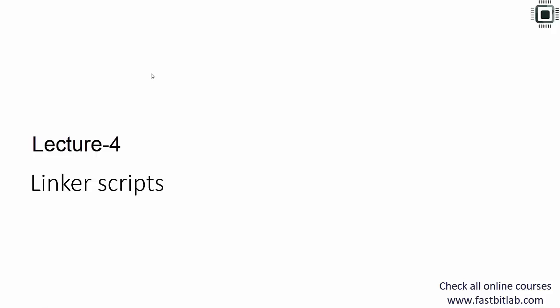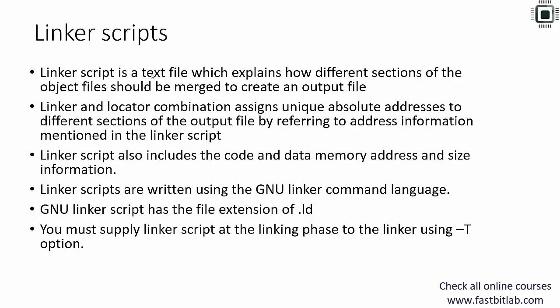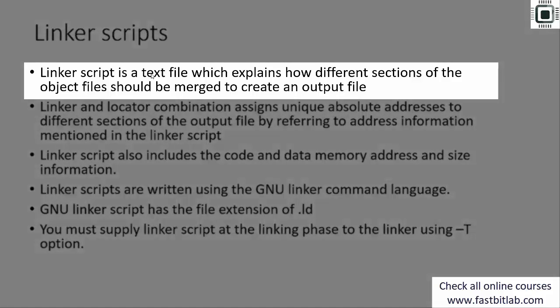In this lecture, let's understand about linker scripts. First of all, let's learn what exactly is a linker script. A linker script is a text file which explains how different sections of the object files should be merged to create an output file.